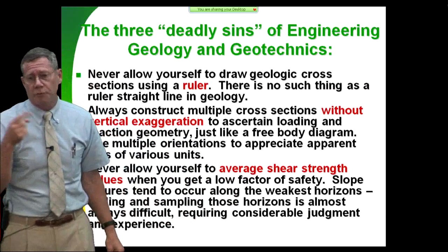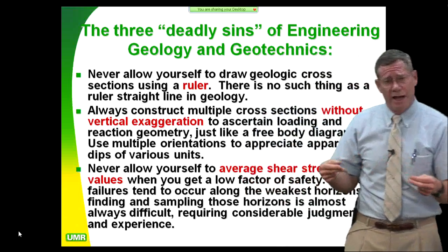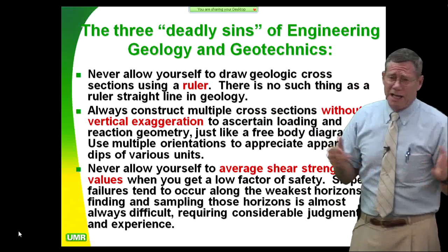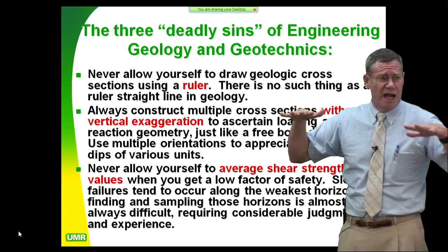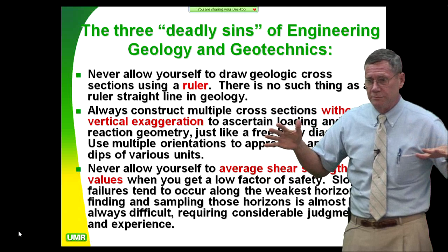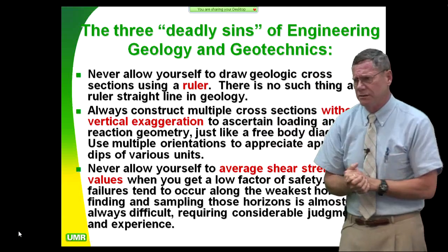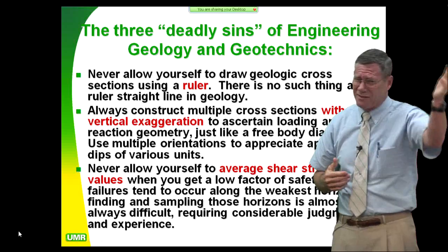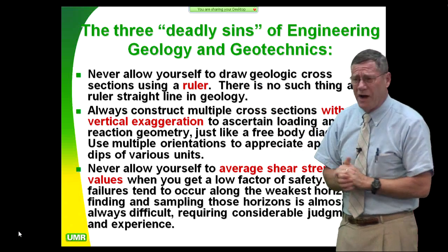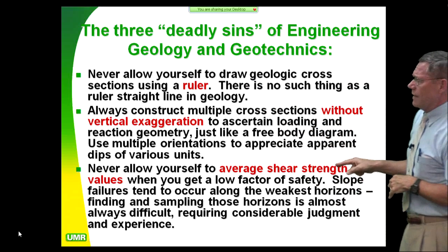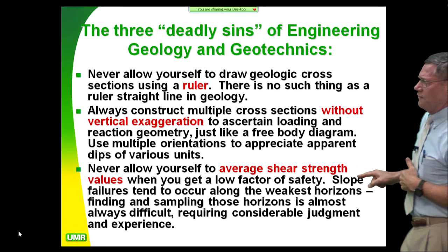And that's a big problem that we have to get over in the 21st century. When you start analyzing them that way, I had them do this out in Sacramento, and 75% of the seepage analyses they did at the design height failed. Just doing it that way instead of the 90 degrees to the axis way, which dates back to the 1930s. Come on, kids, we've got to learn a few things since the 1930s. Follow the water.